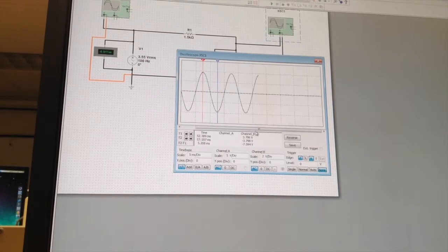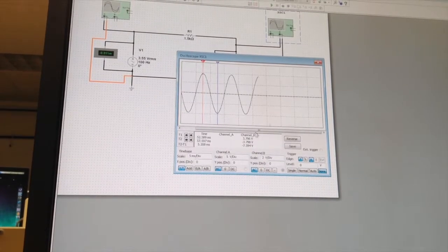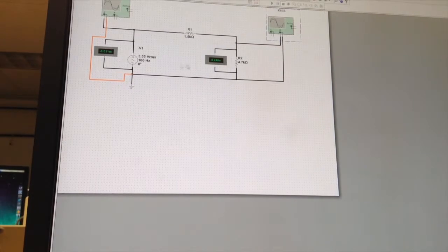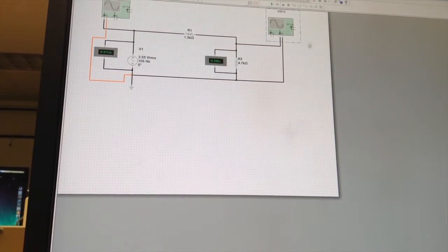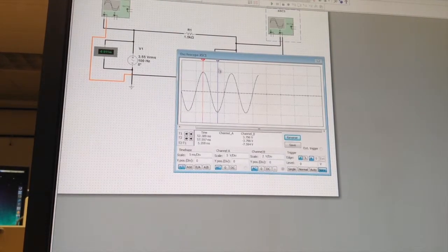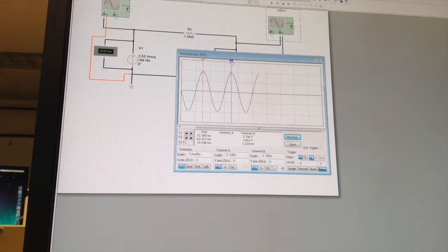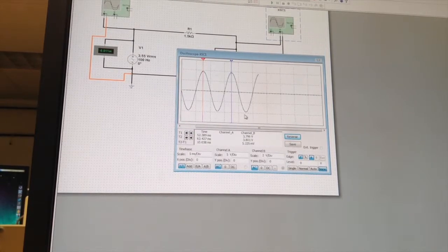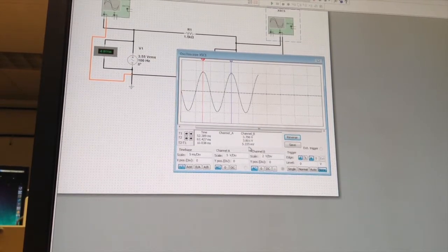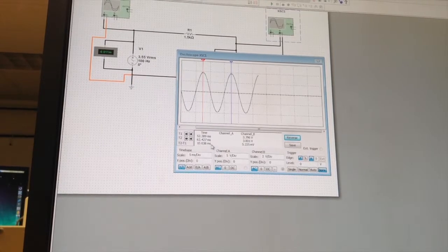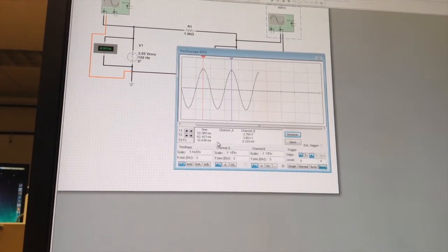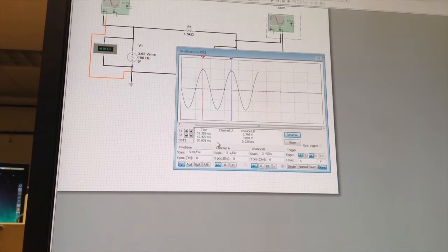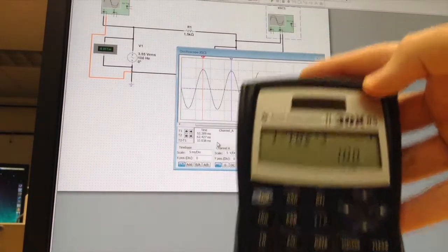And we can see for channel B, it is around 8 volts. The next part we're going to measure is the RMS value, which is the same here, just 3.55. The next is the period. So we go back here, and then we do Ymin, Ymax here, and we see the period for channel B is 10 milliseconds. And then we measure the frequency by dividing that by 10 to the negative third, which is 100 hertz again.